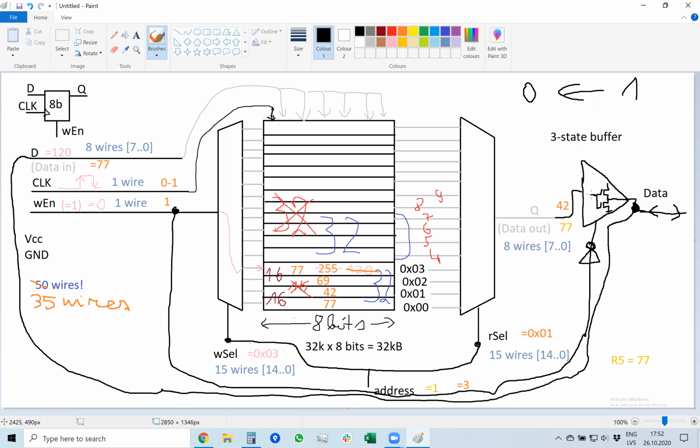But if we disconnect their gates, they don't output anything. They're neither connected to ground nor to the power supply. As a result, this output doesn't output anything, so it doesn't bother the microcontroller's information. And this gate signal is basically disconnected by this write enable signal.